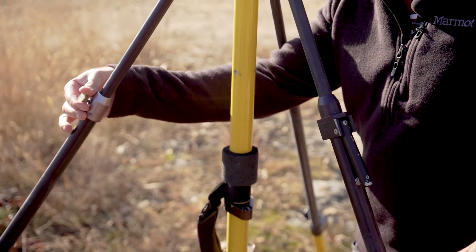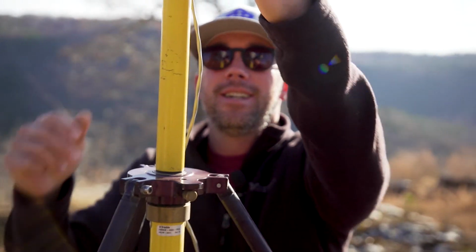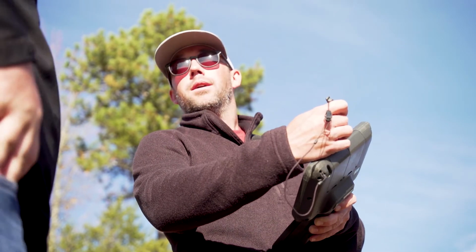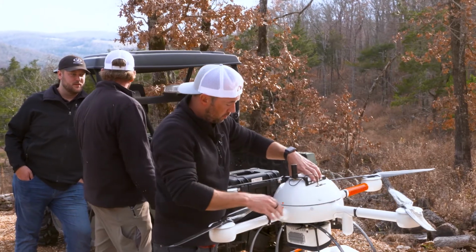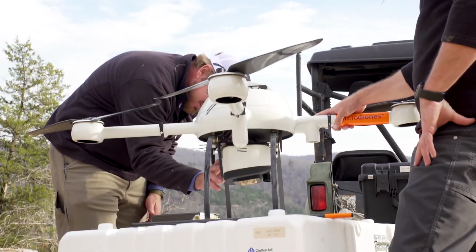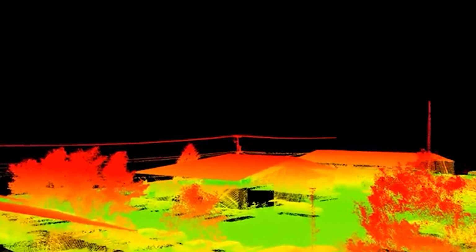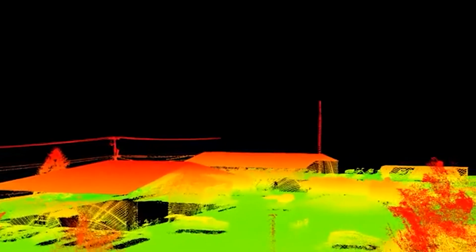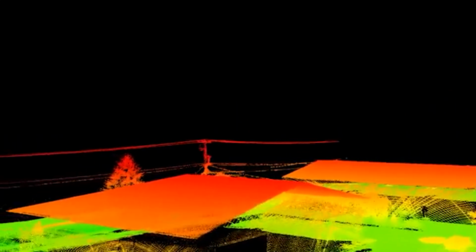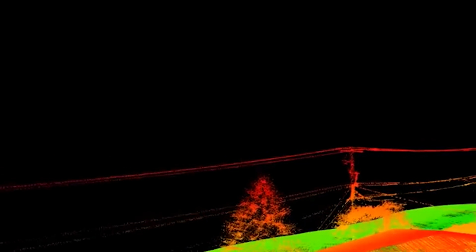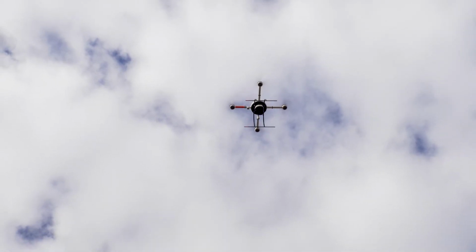Georeferencing transforms the raw data from the LiDAR, providing range and bearing angles, as well as IMU data, providing attitude and positioning data, to point cloud and associated data. With the specifications of the raw data, Microdrones produces a georeferenced point cloud, including all associated data to the point cloud. The point cloud is not only a collection of data, it also contains the uncertainty levels of each point, and a copy of the raw data in such a way that denoising and calibration tools can be used.